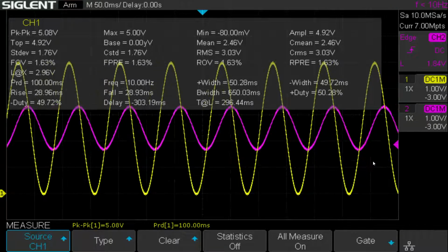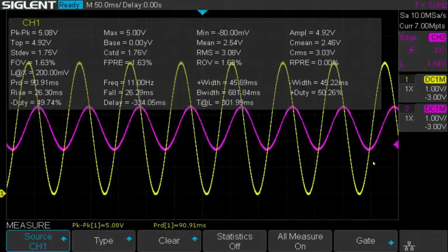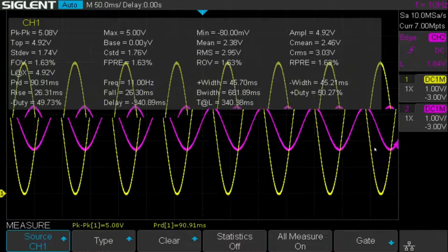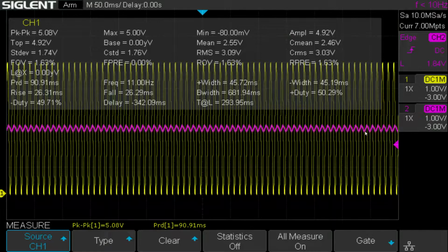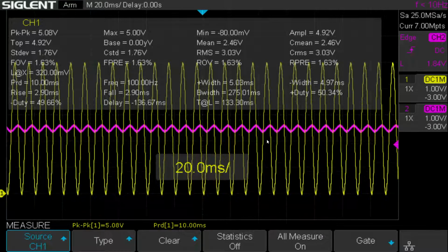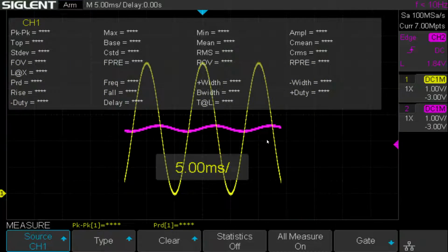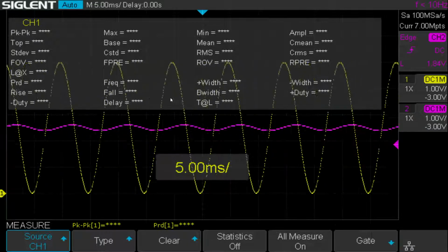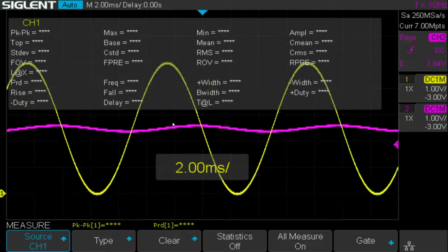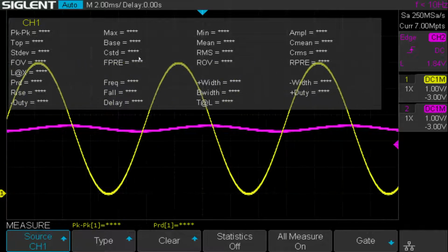I'm just going to go to 100. That should be 100 hertz. And now you can see it's almost like DC right now. It's very flat. So if you have very high ripples, it'll still smooth it out, and anything beyond that is just going to be very smooth. But it's not giving you the 5-volt output anymore.